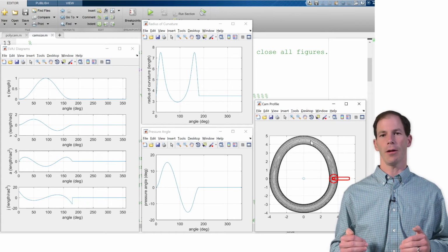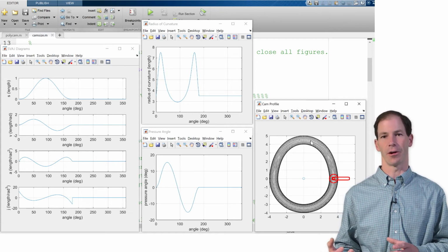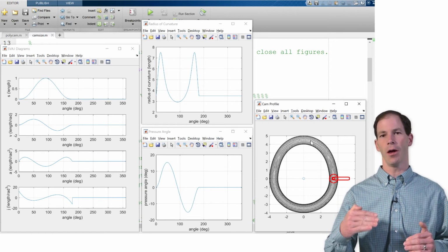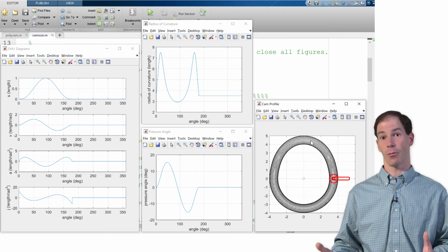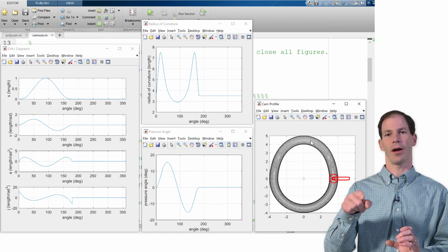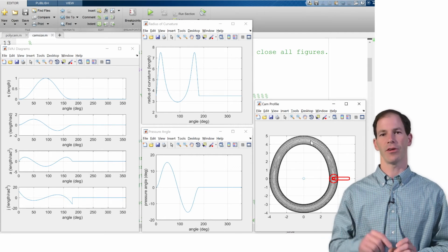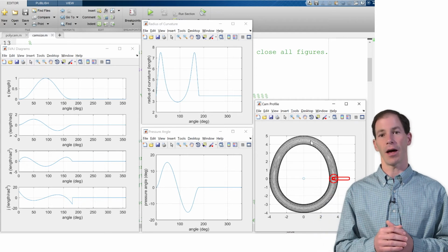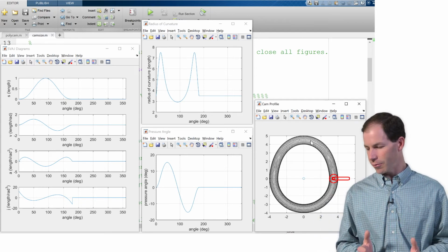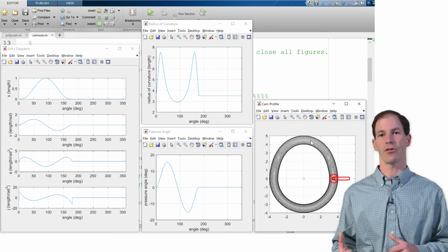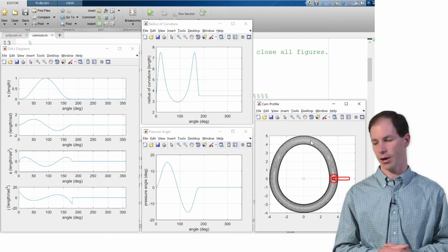Now, the way that we typically build a cam or start to size it here is do a kinematic inversion. So we know that normally I would be taking my cam and rotating it and the follower axis would stay stationary. What I actually do to draw this and to usually do most of my analysis is I invert that and say, let me hold the cam stationary and now I'll move my roller follower axis around the cam sequentially. And therefore I'm going to move this follower axis in the positive direction, the counterclockwise direction. And because of that, you have to then think about the cam as rotating in the opposite direction. So the conventional cam rotation would be clockwise in this case for this design.